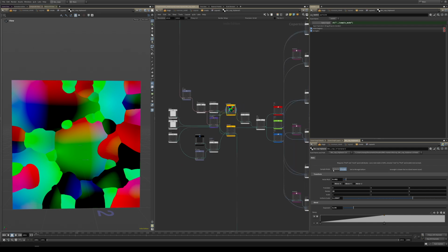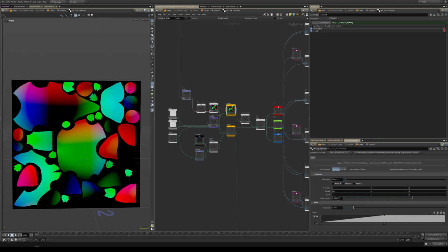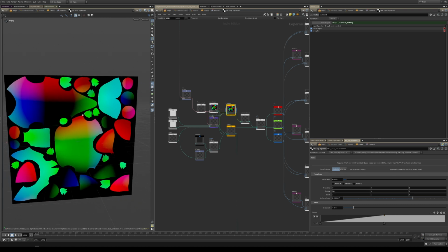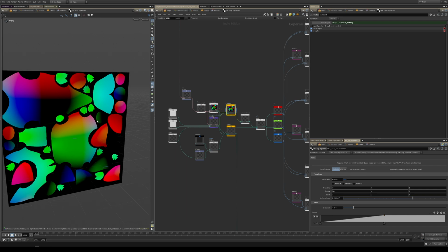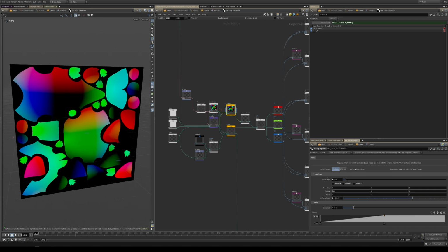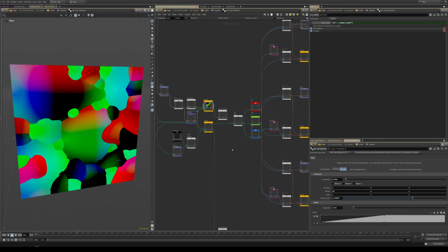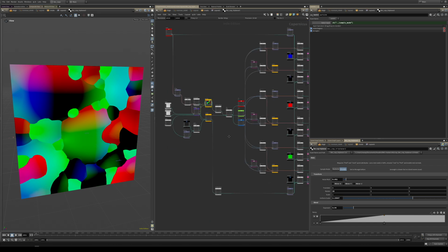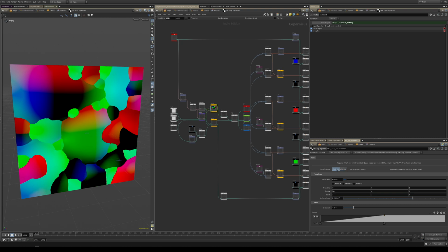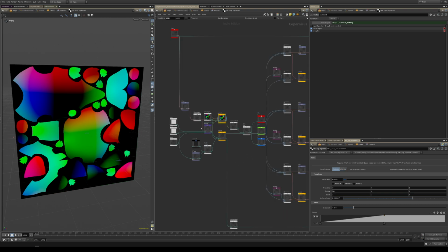And basically the way I figured is you can use this to visualize, have a quicker preview of what you're doing, and then when you're saving to texture, just switch to wrangle, and you should avoid having problems on the seam line of the UV island. So we can keep it for rasterize up to now.